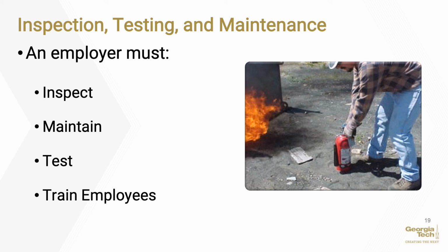Record the annual maintenance date and retain this record for 1 year after the last entry or the life of the shell, whichever is less. Empty and maintain dry chemical extinguishers that require a 12-year hydrostatic test every 6 years. Dry chemical extinguishers that have non-refillable disposable containers are exempt from this requirement. When recharging or hydrostatic testing is performed, the 6-year requirement begins from that date.